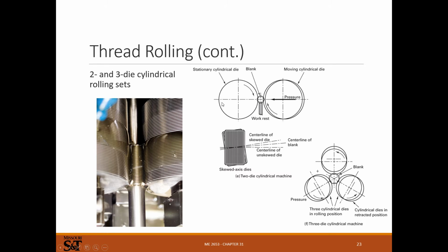Same thing like centerless grinding. You've got two wheels. One of them is going to be skewed. That causes the infeed. And so for all thread, this is how all thread's going to be made in probably most all applications. Yeah, I just don't know why you'd cut it. The centerless roller like this, for any material that's ductile enough to be rolled, this is going to be the way to make all thread or set screws.